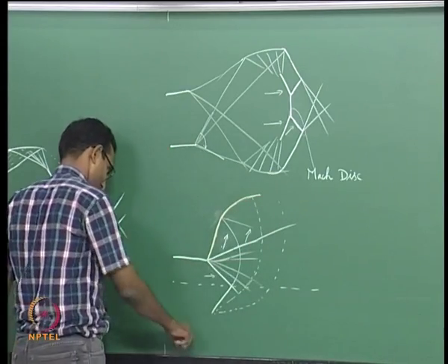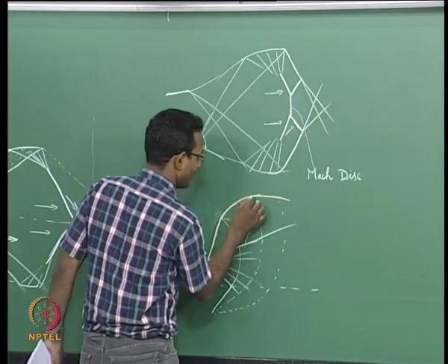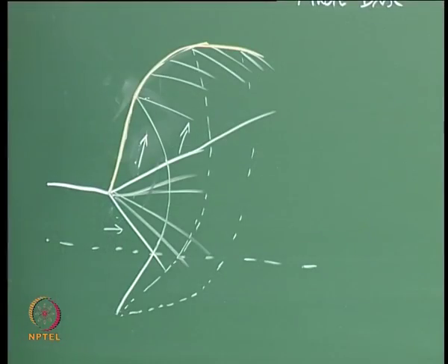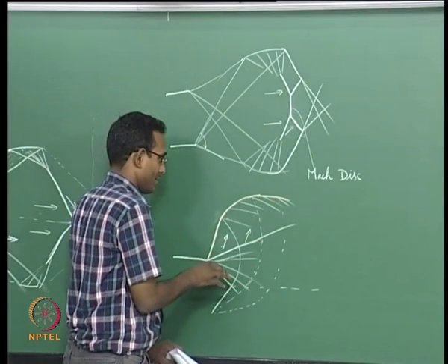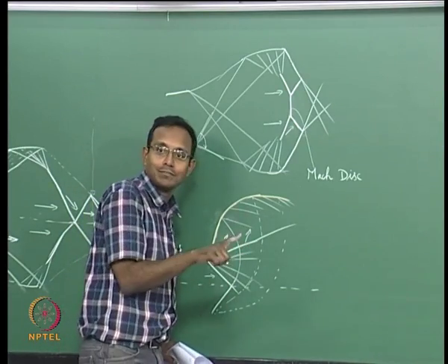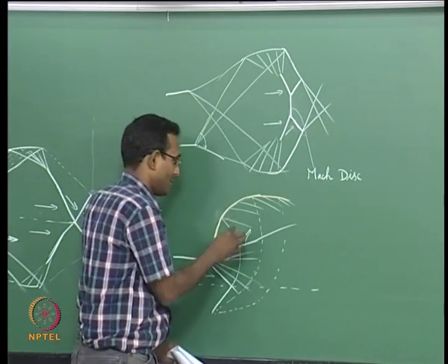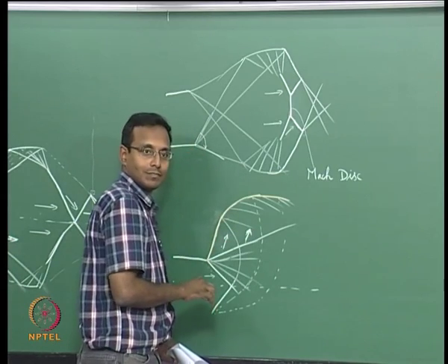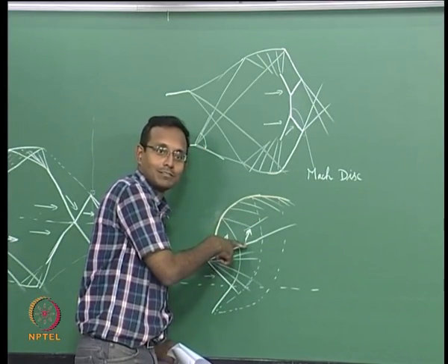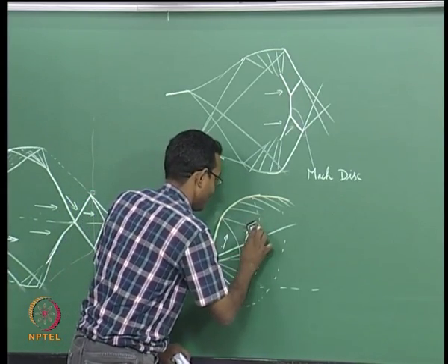All these start to happen, and they are going to get this kind of jet boundary and a whole set of compression waves coming from all of these points. Every point from here will send out a compression wave. When all these compression waves are coming, they are supposed to be right running with respect to the local velocity vector only, which means it need not be going downward. Expansion, when the velocity vector is like this, it may still be running like this, that may be right running locally. I have just drawn it such that it makes it simpler for you to think about it.